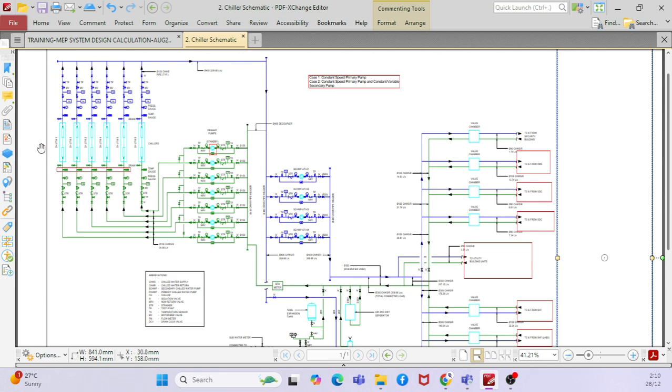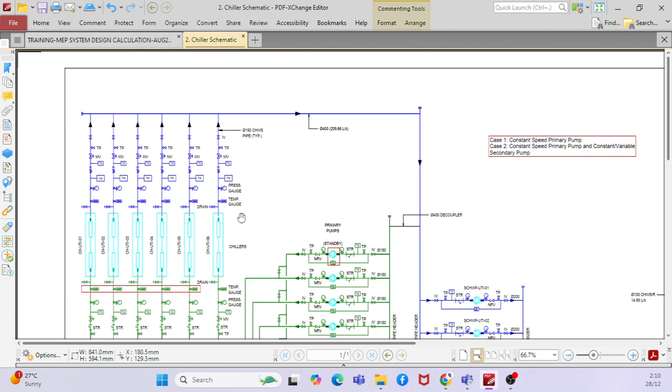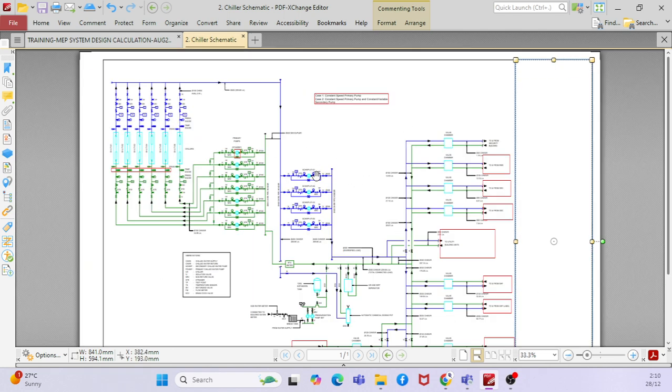Say for example you have a chiller. From the chiller you have a chilled water supply line, which goes to the building, through a pump, because you need a pumping device to pump the water from the chiller to the building. Here you are rejecting the heat, and here you are absorbing the heat. So this is the chilled water network. The supply goes to the building, absorbs all the heat, then comes back to the chiller. Here it is rejecting and here it is absorbing. Basically it is the same as a refrigerant cycle. Is it clear?